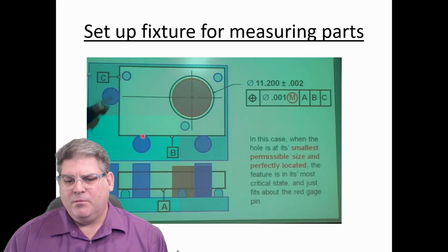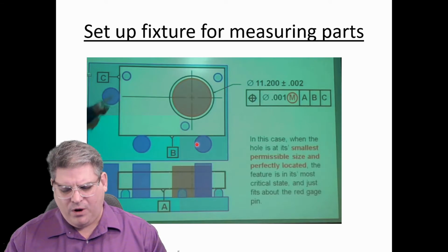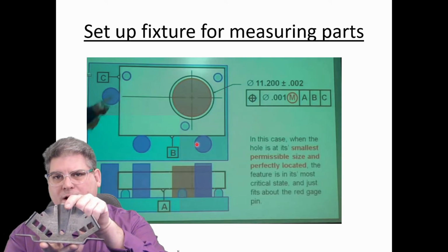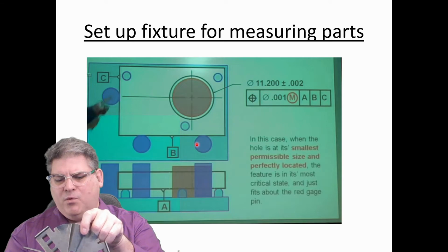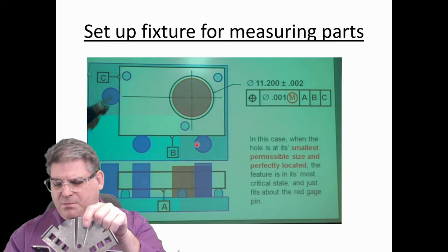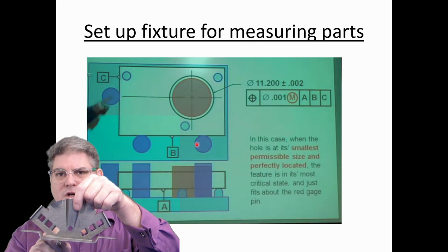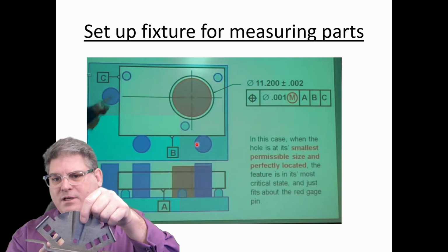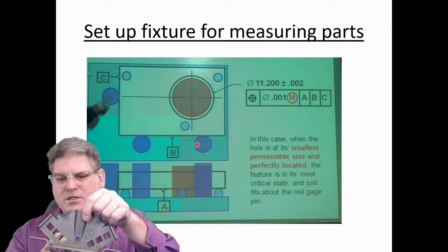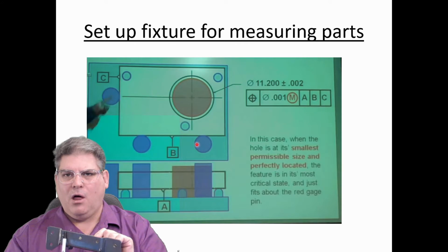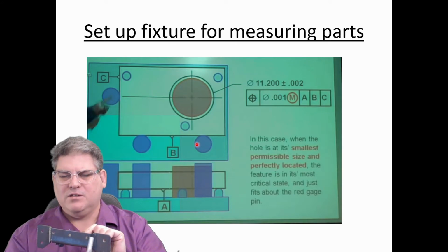B plane is refined by these 2 rollers. Okay, so again, 2 points. 2 points in this case makes a beautiful line, right? And so again, we're using rollers because the contact point of a circle on a line is basically 0. So by having 2 points, we're able to take away a lot of deviation of this surface.